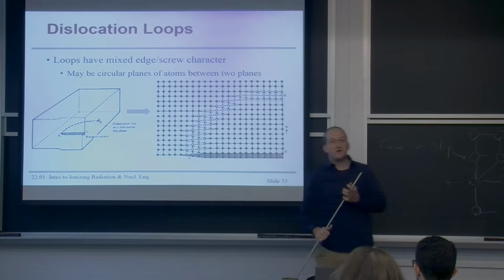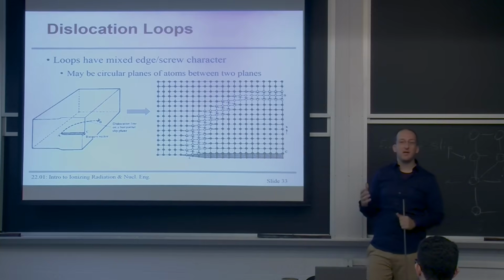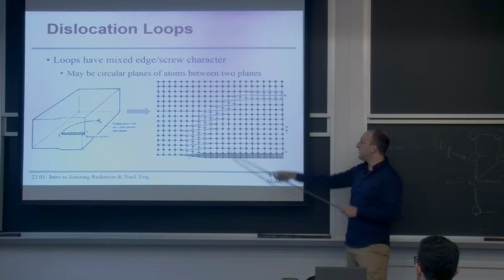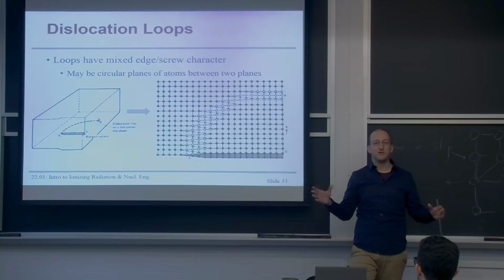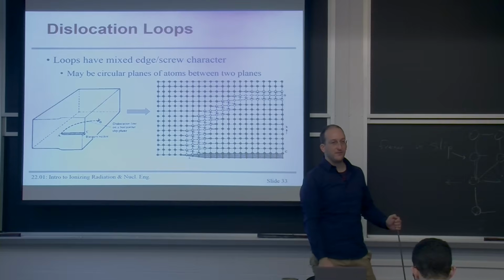So when you stress out a dislocation loop, it just grows. You're not actually creating or destroying matter, but what you're doing is causing this small loop of extra half plane of atoms to grow further and further until it actually reaches some obstacle or the outside of a crystal.